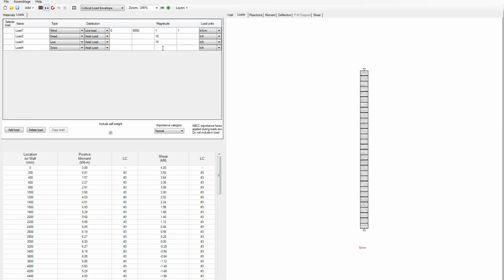axial load. Now it's important to remember with the MASS software, we are just designing an element of a structure. Whether you model this as pinned or fix the base all depends on the other assumptions involved. The loads are also not distributed to the walls by the software for the out-of-plane module. This is something that you do yourself, and all of the assumptions and numbers that you put into this module, MASS will design for. So for any assumptions regarding tributary areas, if you have, let's say, a large door on one side of a wall that you were designing, you need to take into account that you have a larger tributary area and scale up your loads accordingly.